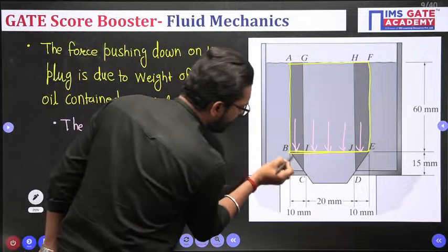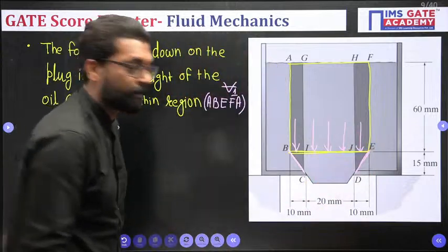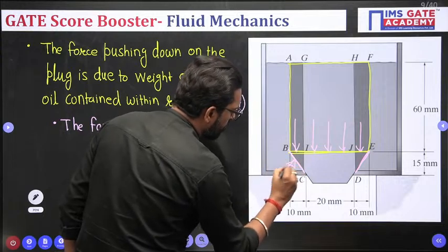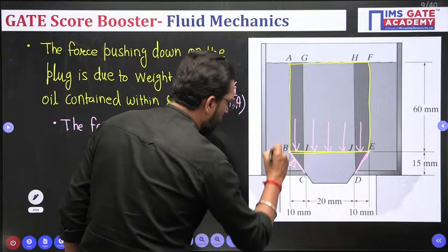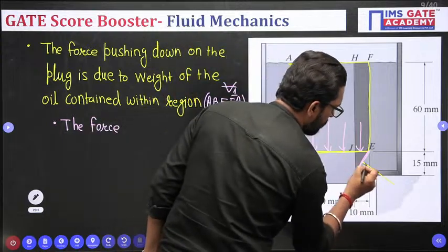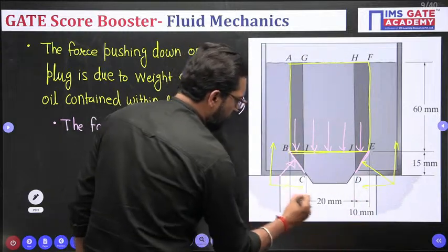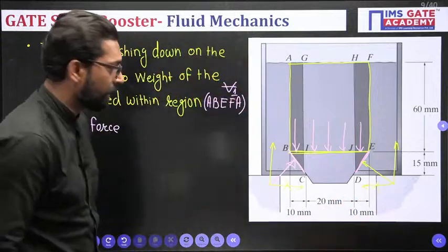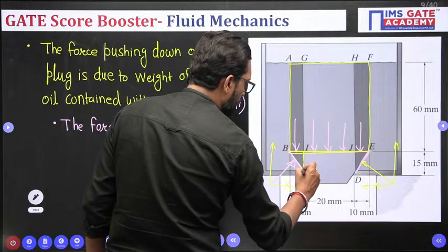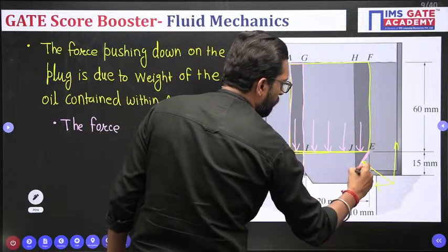Now, this is a slanted surface. On this slanted surface, a perpendicular force will be produced due to this fluid. This perpendicular force has two components, one is upward, the other is horizontal. The two horizontal components cancel out. Why? Because they are both symmetric. So the total is this one. This slanted surface projects upward, so if you project, this is your projected.